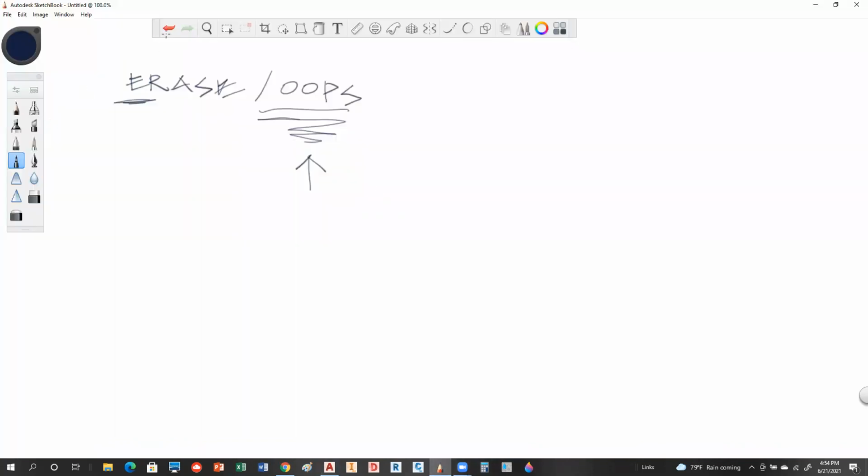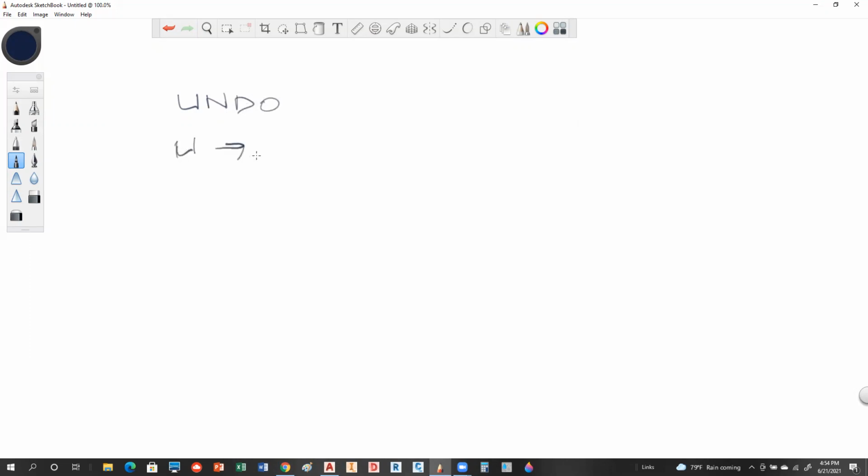These are called the undo and the redo commands. Now most people are familiar with this concept because other programs also have them, but you've got to be a little sure what it's doing. So we have the undo command in AutoCAD. Now you can also just use the U command, which is basically undo one step. This is probably one of the safest ways to do it because it's stepping you back one step at a time.